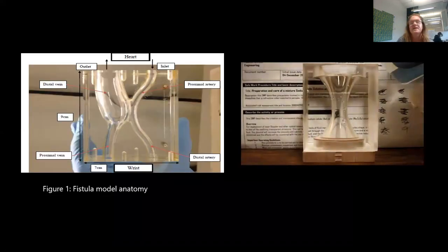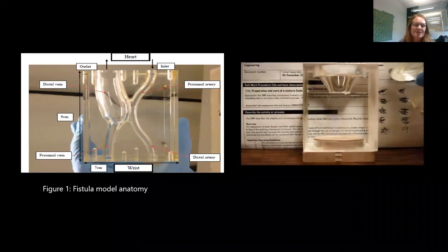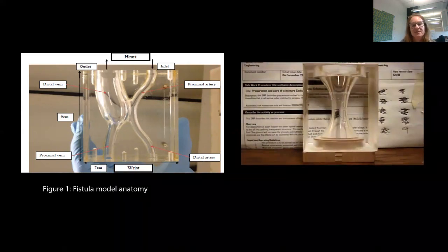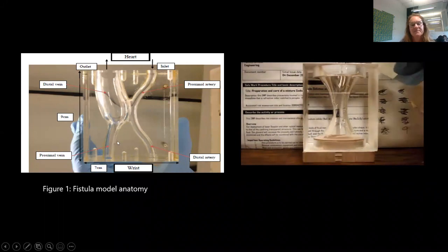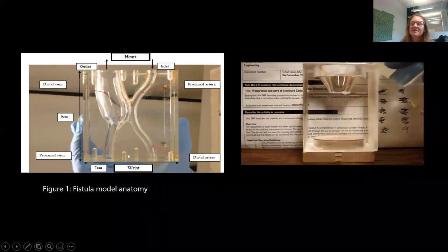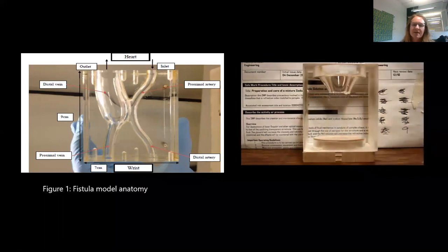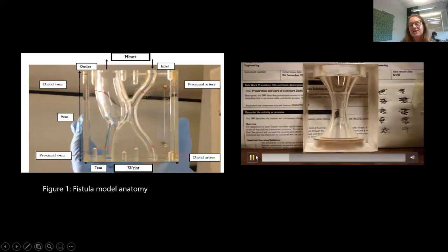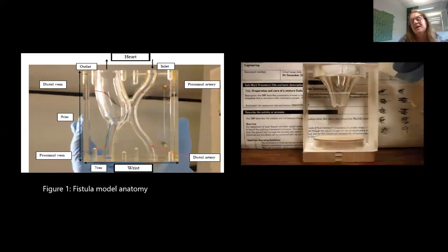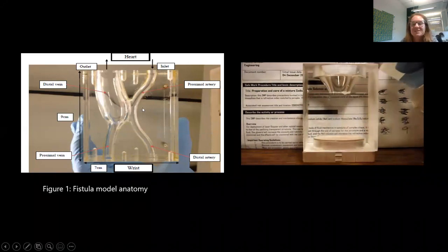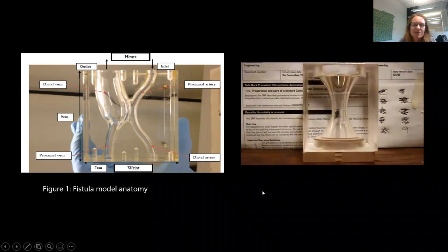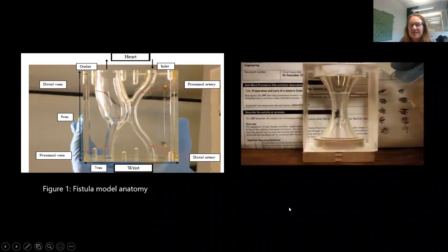Now, we then started to look at the actual fistula shape, and to begin with, we made an idealized shape. This one was actually machined out of acrylic in our workshop, and we made a side-to-side one where you can see that both the vein and the artery go down to the hand. By using a fluid that's got sodium iodide in, which matches the refractive index of acrylic, we were able to make this geometry pretty much disappear, which is useful because we do mostly laser measurements, and obviously we don't want to have any of this refraction happening.